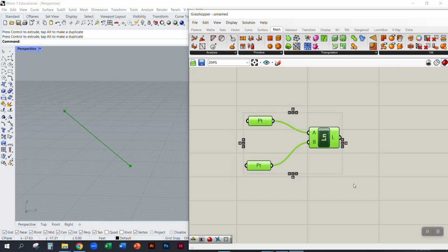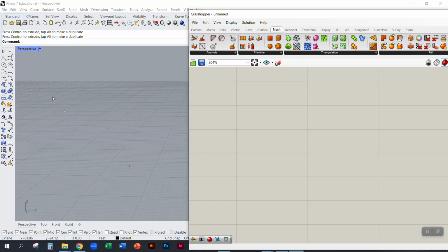So in today's tutorial, I'm going to show you something similar. I'm going to show you how to create a series of curves that we generate a surface out of in Grasshopper. Okay, and I'll show you the process, and I'll show you how each step of the way everything is adjustable, everything is parametric, so you can change all of these parameters and generate new geometries.